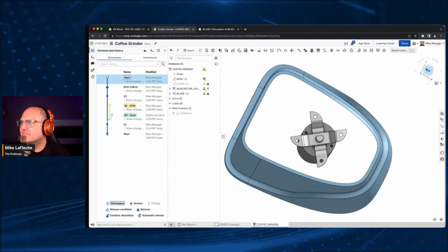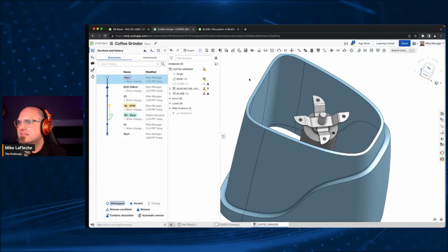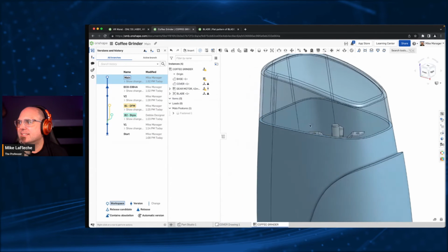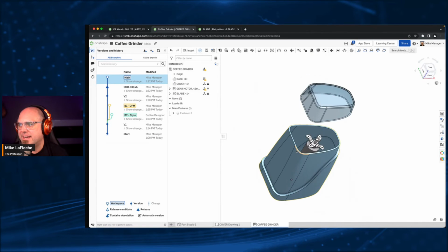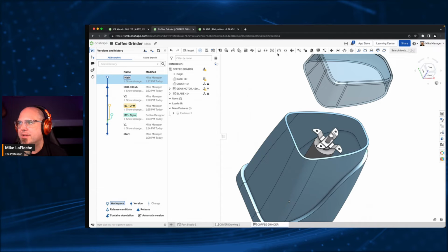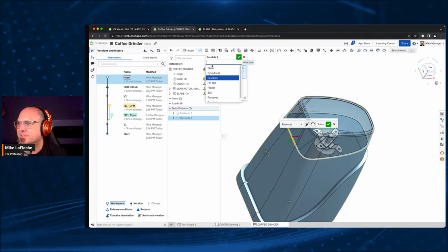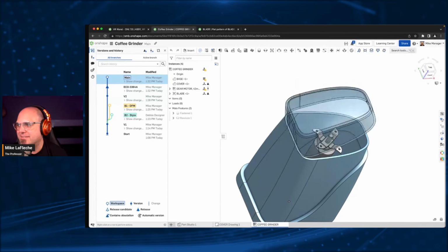The next step is, let me turn on the cover again. You can have other kind of moving relationships. Like if I want a simplified kind of hinge here, just defining a common interface right now, I can hover over this edge right here, hover over this edge here, and I'm going to use a revolute mate. And now, it's mated, so this thing kind of hinges here.